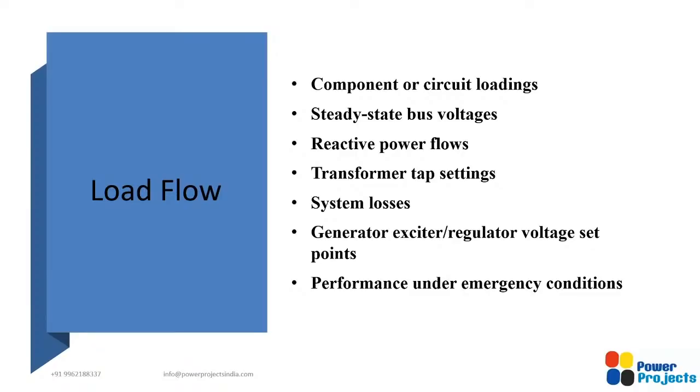But one important aspect which you need to work out or verify in a load flow analysis for large scale interconnected power systems, like when you are performing the load flow analysis for the entire India, then you need to really look at steady state stability also. That is steady state stability by means of checking the angle of each and every bus and finding out what is the maximum angle difference between two different buses. So that you need to check.